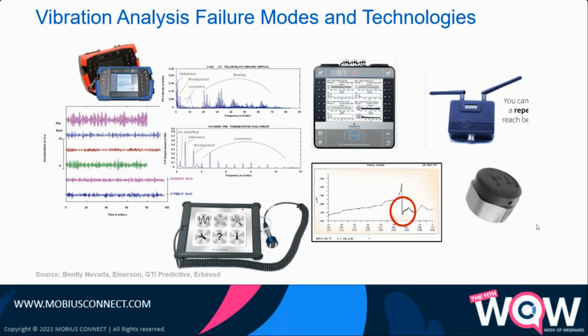Vibration analysis, again, has been used for many, many years. It can be used in a route-based and or connected environment. Route-based is typically done on a monthly basis, where you have an accelerometer and data collector, and you walk a route and collect data on your rotating assets. Connected solutions are able to monitor these assets on a continuous basis or a much higher frequency, every shift, every day, once a week, et cetera, right? Next slide, please.